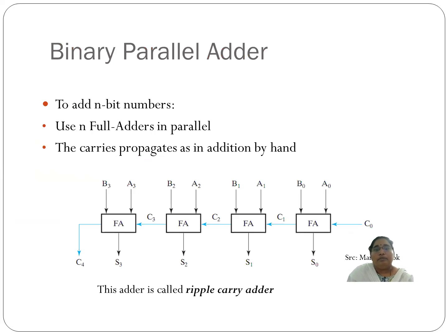So this is a ripple carry adder. Hence we are achieving here in this circuit a 4-bit addition. If we want an n-bit addition, we just need n full adders to be connected in a similar manner. N full adders starting from the least significant section, propagating towards the most significant section, and the resultant will be an n plus 1 bit number because two n-bit numbers when added, there is a possibility of carry generation, that is 1 bit.